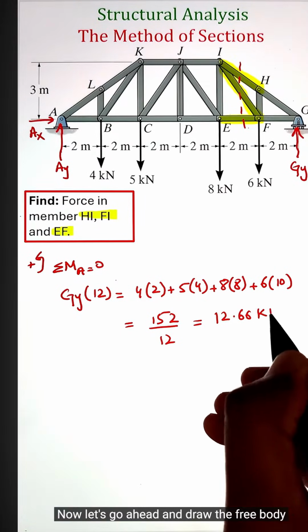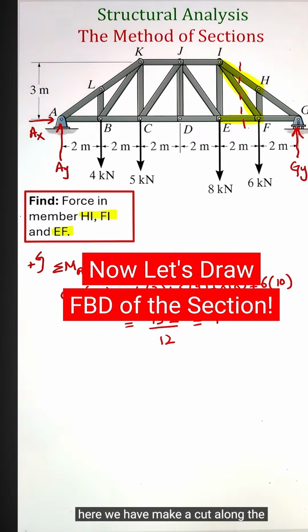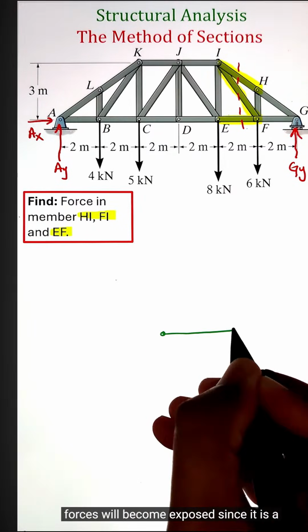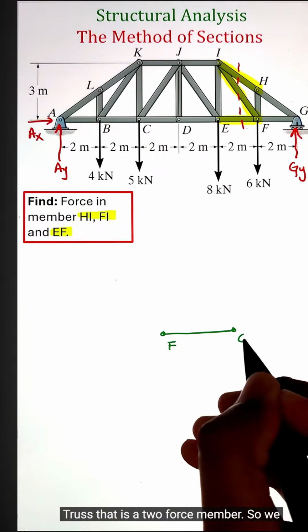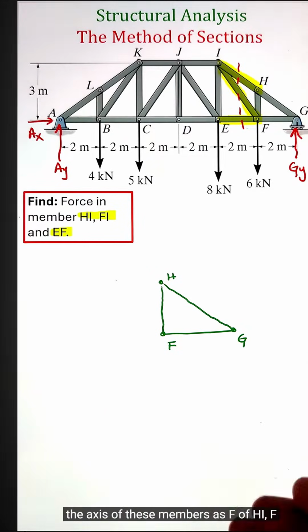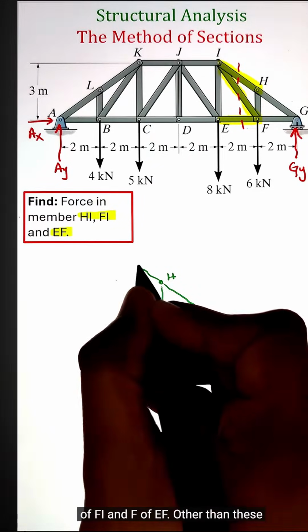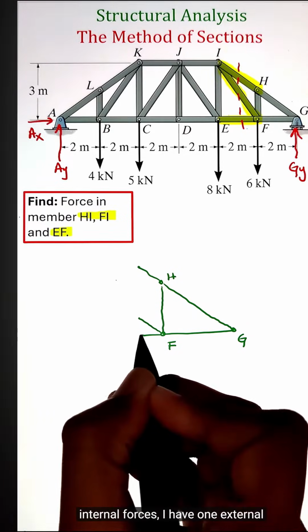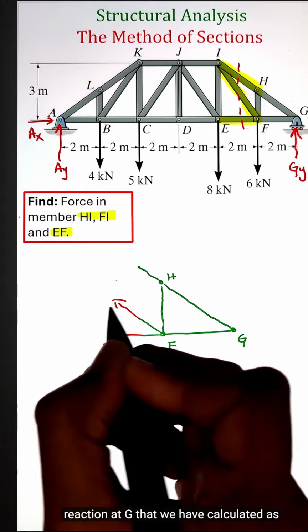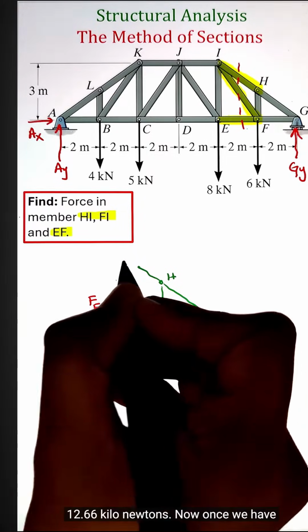Now let's go ahead and draw the free body diagram of the smaller section. Since here we have made a cut along the members HI, FI, and EF, the internal forces will become exposed. Since it is a truss that is a 2-force member, we will only have the force acting along the axis of these members as F_HI, F_FI, and F_EF. Other than these internal forces, I have one external force of 6 kilonewton that is applied at point F, and then we have a support reaction at G that we have calculated as 12.66 kilonewtons.